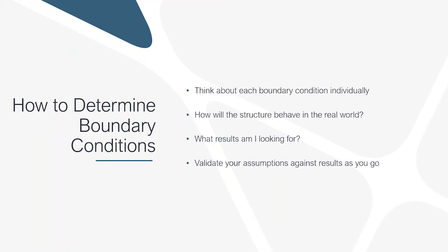And so that's an important piece. And then probably for me, the most important thing in determining boundary conditions is just testing things as I go. See if the structure behaves like you expect it to when you load it. This requires some understanding of load path and definitely structure behavior. So it's good to make sure you have some idea before you go in of what you expect to see when you get to the end. And to be fair, when you're using FEA, a lot of times you may not know the end answer, but you also do have fundamental knowledge of structural behavior that you can use for some deductive reasoning to determine maybe what it shouldn't look like. I've definitely had situations where I don't necessarily know what I'm looking for, but I know for sure that the structure shouldn't be behaving in a certain way, and that I've got a boundary condition issue. So breaking things down piece by piece and testing the movement of the structure is a really good way to figure out if you've done it right.